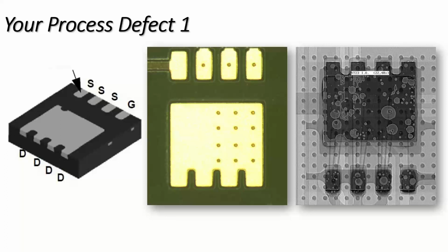And if you can do that by clever stencil design, but still giving you the right volume of solder, then that's a benefit. And one of the ways I do that is I put resist donuts, resist circles around the vias. And then you print around the area, and the paste during reflow does not go into it, and that reduces the possibility of voids forming.